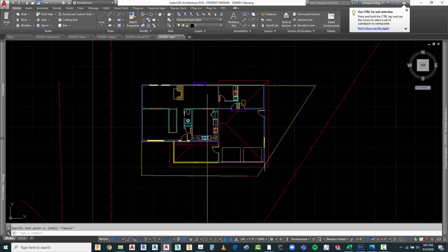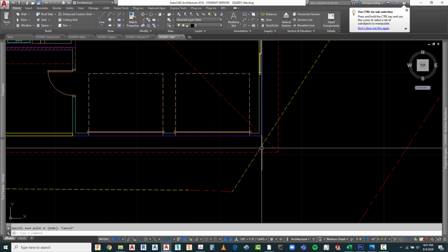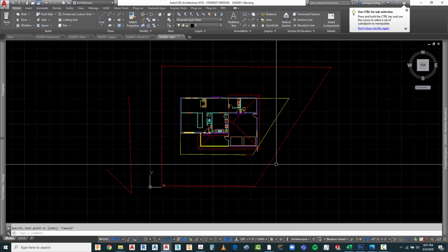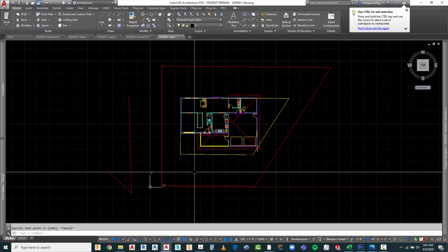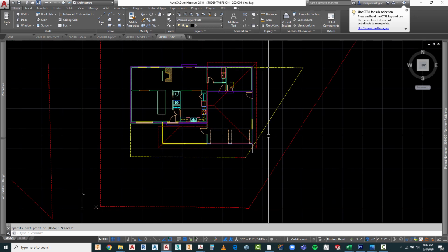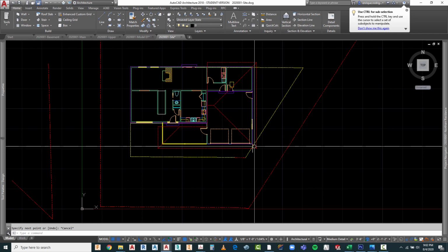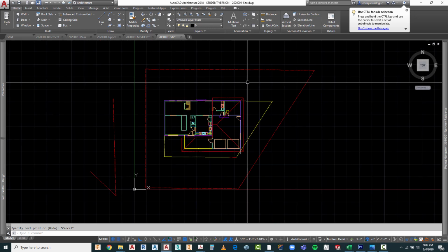Now once again, rather than moving my main level down from this point to this intersection point, I'm going to move my setback lines, my property lines, and my north arrow up so that I'm pushing the house as far forward. Again, that's a figure of speech, because I'm actually moving the property up so that I'm giving myself as much backyard as I possibly can.